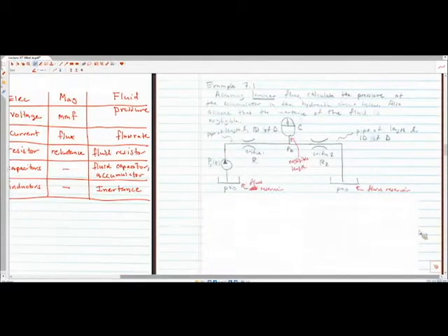is we have a system. It's pretty simple, but we have a pump. What a pump is doing is taking pressure from ambient and elevating the pressure. So we have a pump and it increases the pressure from the low side, basically just a tank of fluid it's taking it from, and then in the high side it has some sort of higher pressure to it. The system's pretty simple. It has two orifices which create a higher resistance, and it has an accumulator in the system which has a capacitance associated with it, and then it dumps into this.